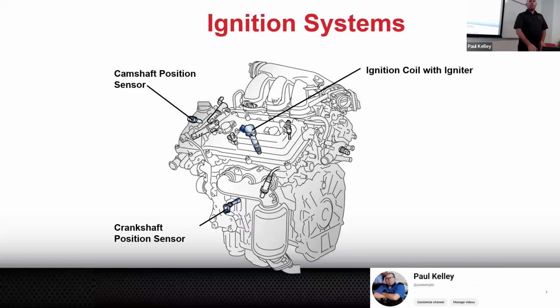There's 2 more problems with that. One, I don't want you to ask me a lot of questions about this. I'm just going to tell you what could happen, and you probably have an idea of how I know this. If the vehicle has, let's say, a fuel leak, or if you just did some work and there's gas fumes around here, and it sparks right here, what do you think's going to happen?